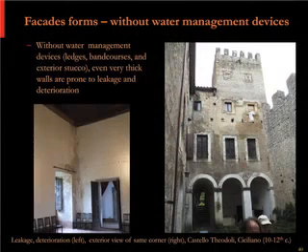So if you look at the lower left, water comes in, and it has a triangular gradient. It's moving downward due to gravity, and it's also moving inward due to absorption and capillary action. So it creates that triangle. And what these ledges and band courses do is they catch that water like a flashing, and they direct it back out. So on the photo at the left, they're resetting the clock at each stage, bringing that water out, and it starts all over again to avoid leakage at the interior.